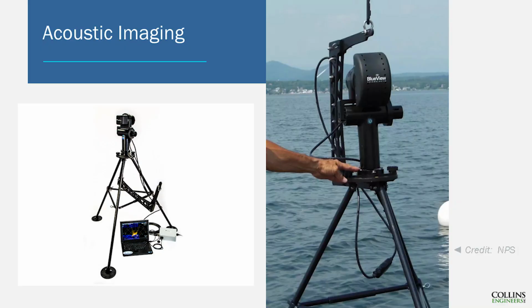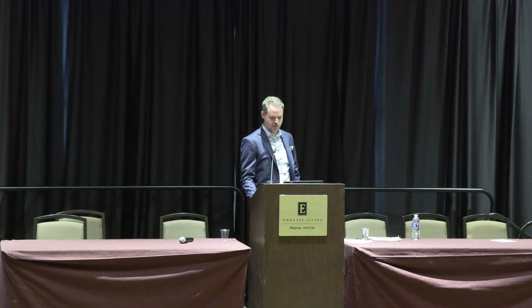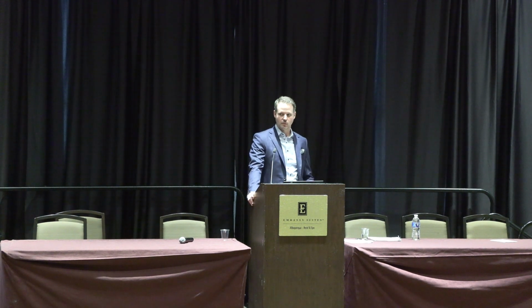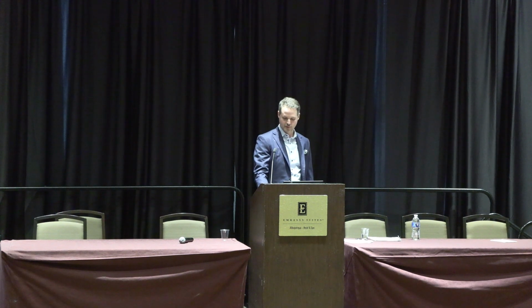So here's a slide of the BlueView in its most common tripod-mounted configuration. This is usually the best for performing bottom scans or the vertical faces of structures. A limitation of this one is that it doesn't perform well in heavy current, like at Lenore, because it'll just fall over unless the legs are heavily weighted, but then it's pretty cumbersome to use. It'll also have trouble seeing beneath structures such as a bridge footing or something like that, where you might want to see the extent of undermining. So that's why this configuration was not chosen for this project, even though we do use it a lot on other things.